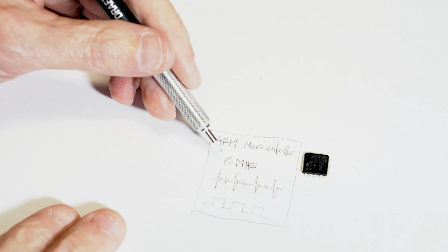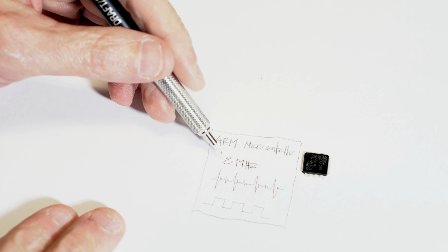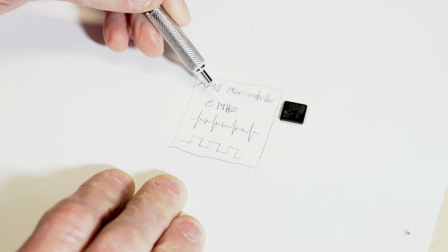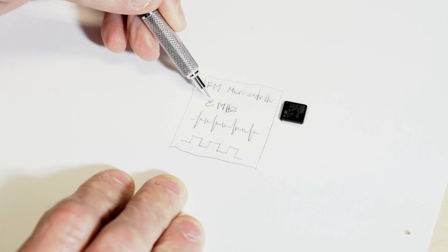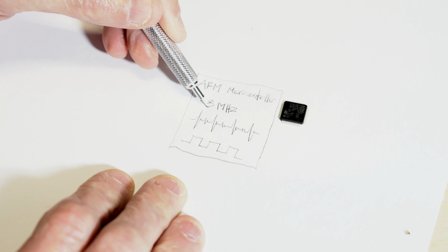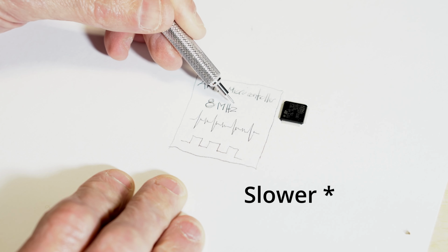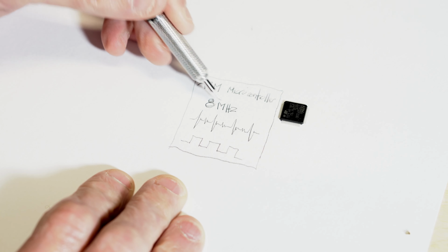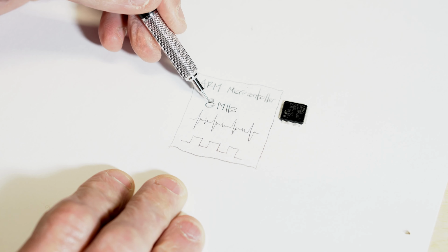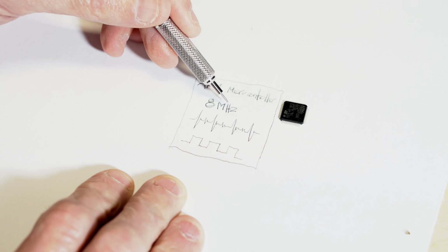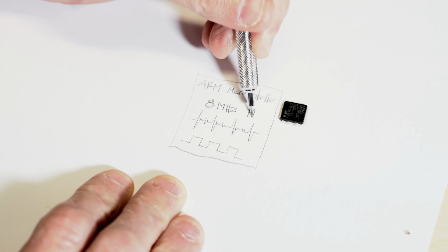So this is the internal oscillator, which is already available to you. The speed of this internal oscillator can be varied. You can pre-scale this, or you can divide this into a smaller speed, like maybe 4 MHz if you wanted to divide it by 2, or you can increase this speed using the PLL, which is a multiplier.